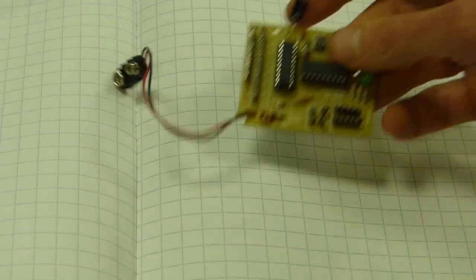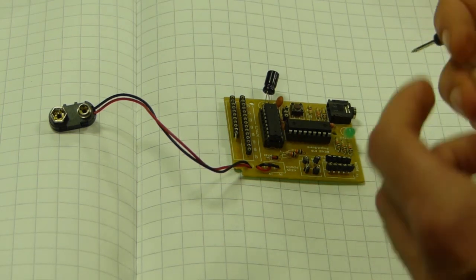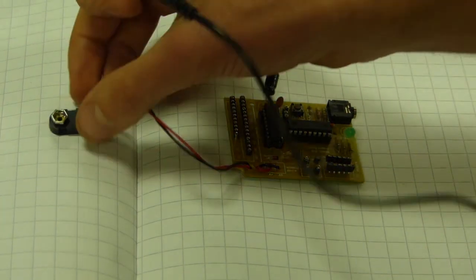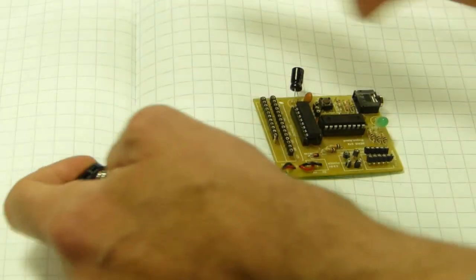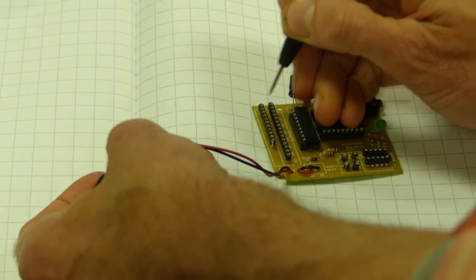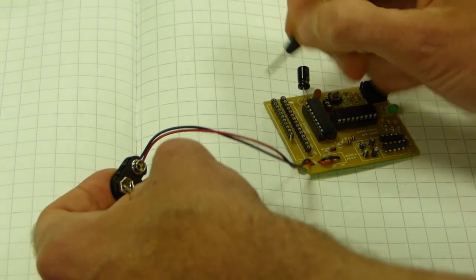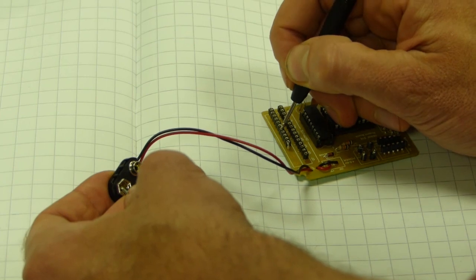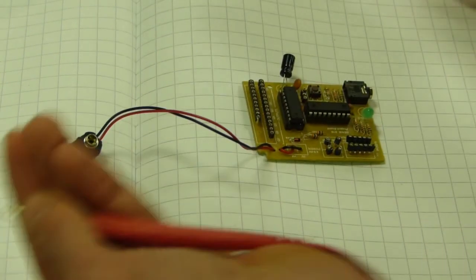So you can see where things are electrically connected where they shouldn't be, or vice versa. So for example here I might be looking for a fault on the positive rail. For some reason there might not be a positive connection. I can hold that there. Actually it's that one, sorry. And yeah, I can check all of those positive terminals are connected up just by hearing that beep. It's a really useful feature, that.